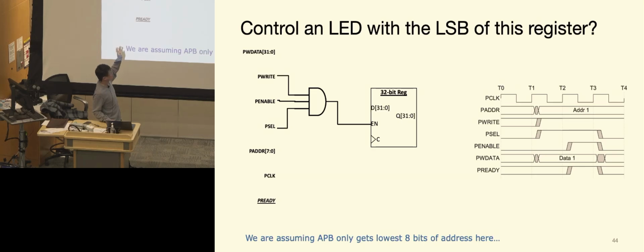Those are three different signals going inside the peripheral bus, but only one connects to the register, because there is only one enable on the register. They're doing a logic AND here, so this register only gets enabled if all those are true. It saves space and everything. And the 32-bit data line goes to the data line of the register. That was pretty straightforward.